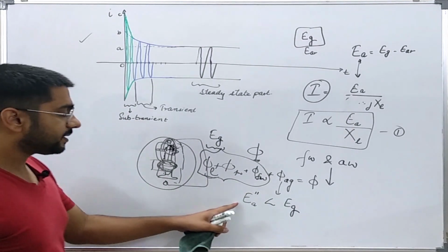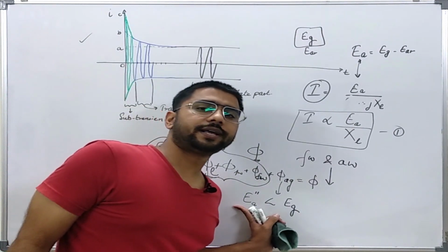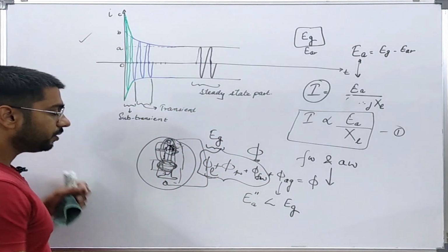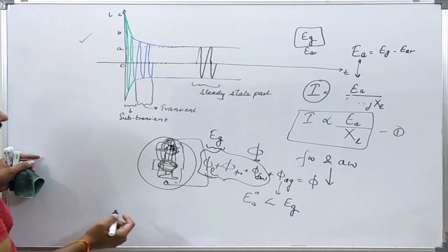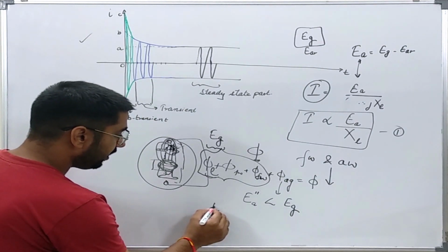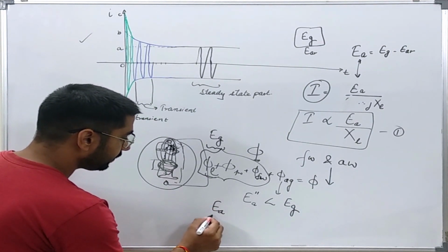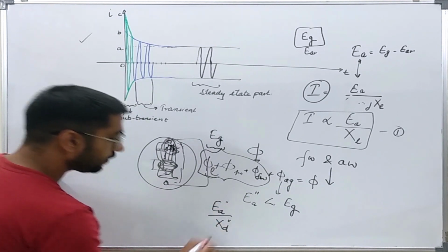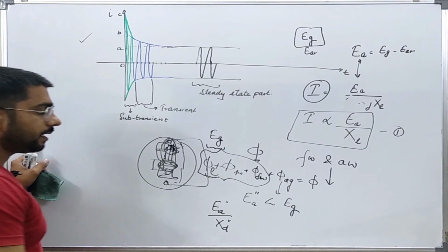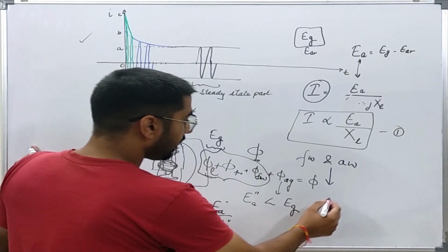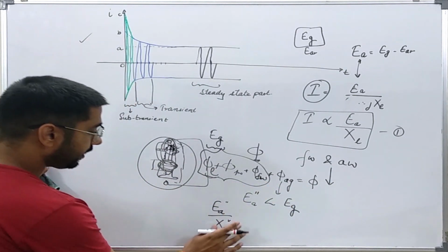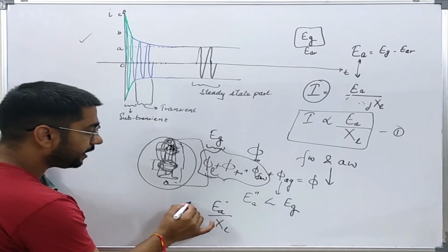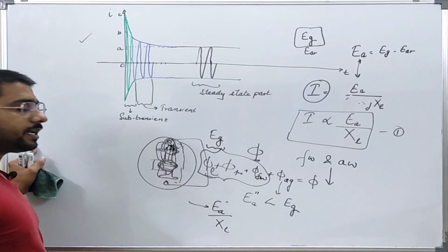Let me call this the sub-transient induced voltage in a previously unloaded synchronous generator. Now the short circuit current will be simply, sorry, not Xd double dash, XL, since I am taking the final induced voltage in the air gap.